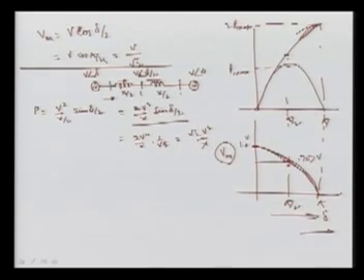And this value, when it is pi, is unity, and then this P will be twice v square upon x, at delta equal to pi. So this shows that now this is twice P max, and we are going to here. This is the characteristic if we can maintain the midpoint voltage.